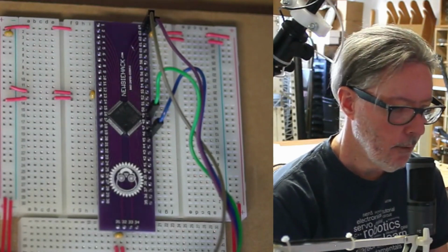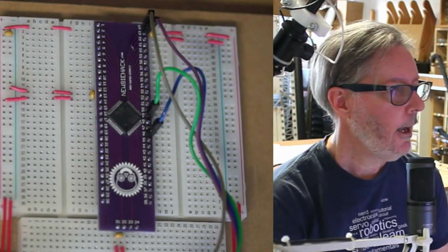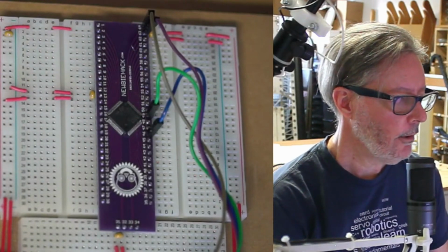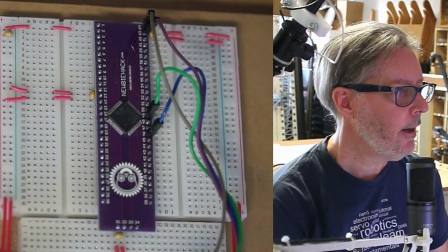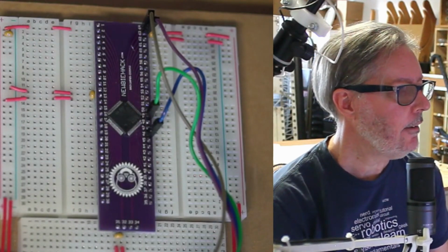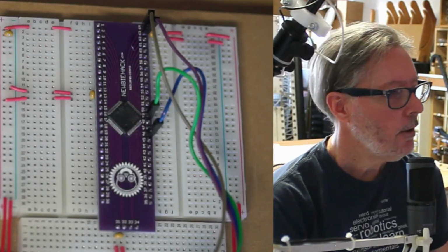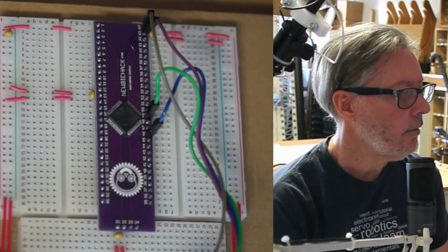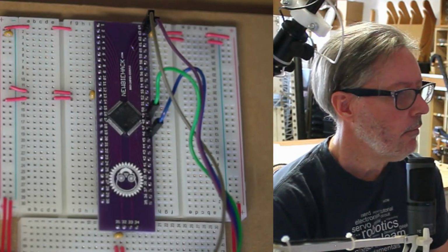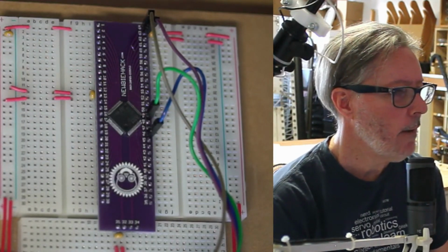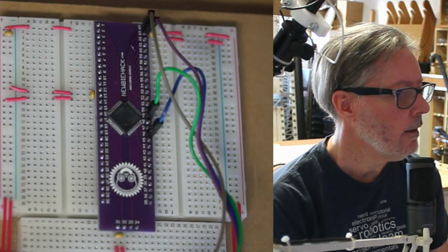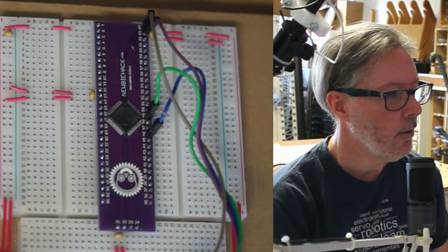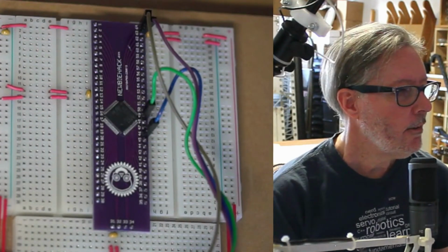Because other microcontrollers have more than one ADC, this particular one has only a single ADC, so it's not specifying 1, 2, or 3. It's just ADC. But in the programming, you still have to put the 1 because this is programming macros. They set up the macros for multiple microcontrollers, so it just makes sense to do ADC 1 just in case you have a microcontroller that has more than one ADC. All right, so this works.